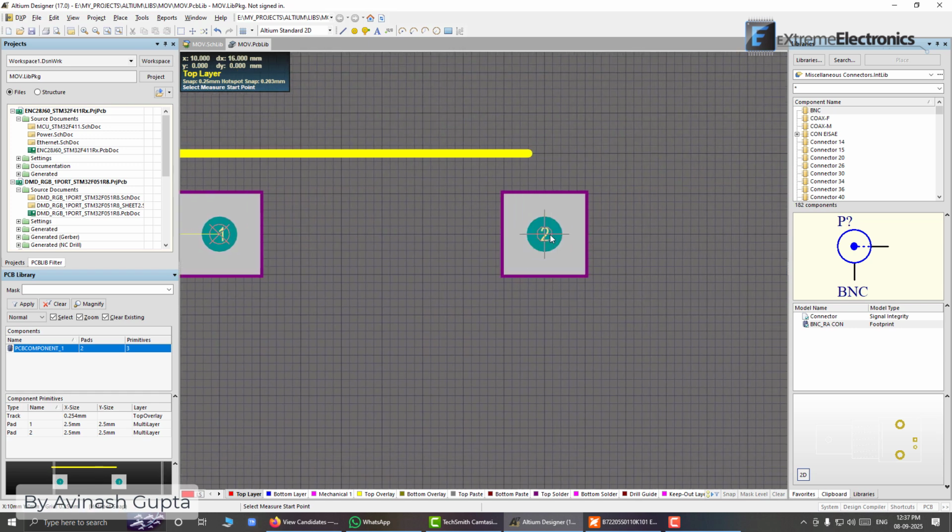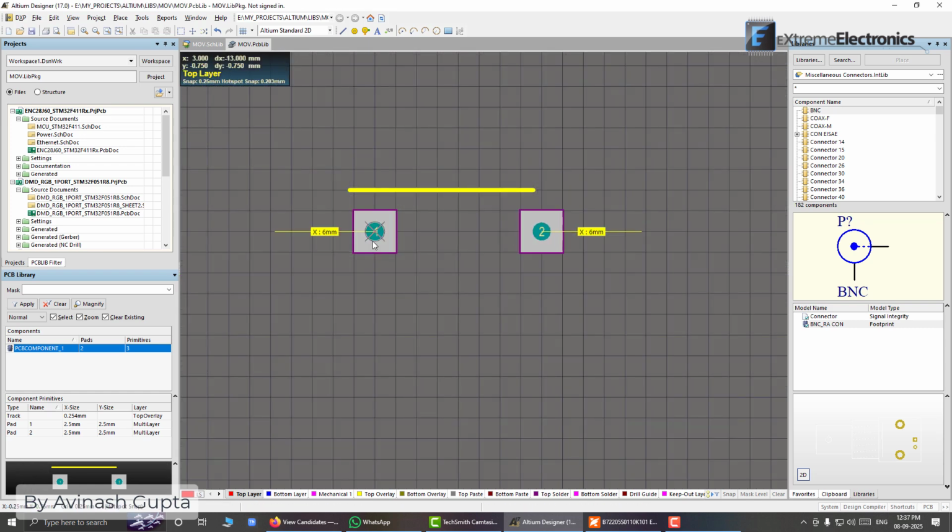Same we have to do here also, from the pin 6 millimeter on the other side. Great, we have 6 millimeter. So we have to draw the outline till this point. So let us extend this to here like this and like this, and let us select this one and Control C, and we have to mark the origin. Let us click here. After that it will be copied.